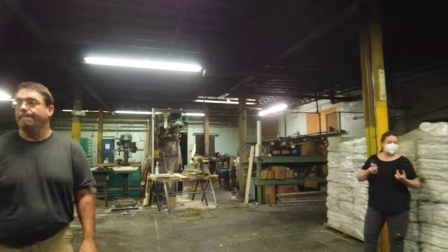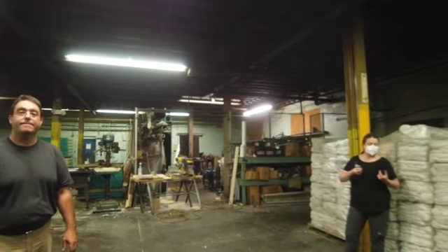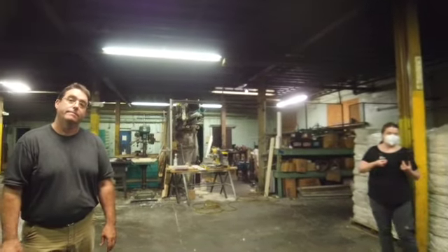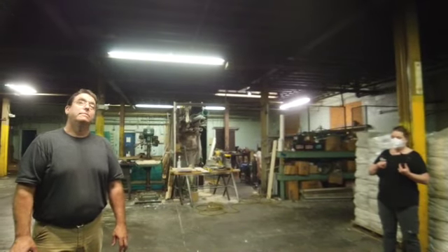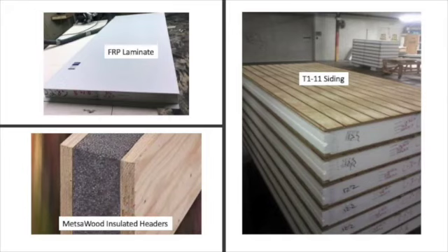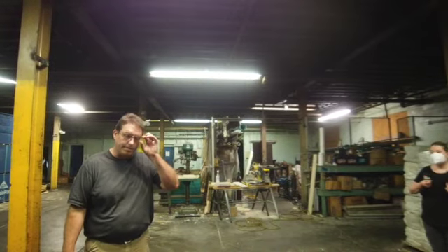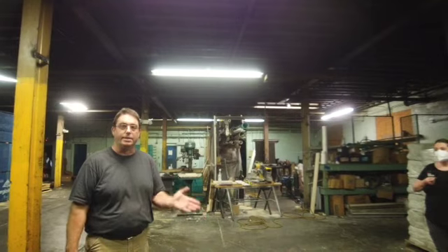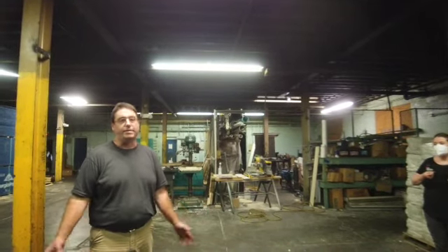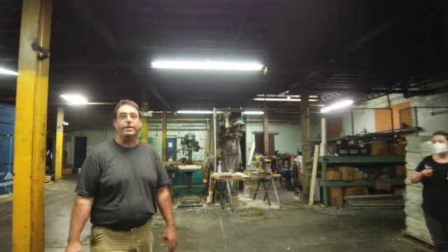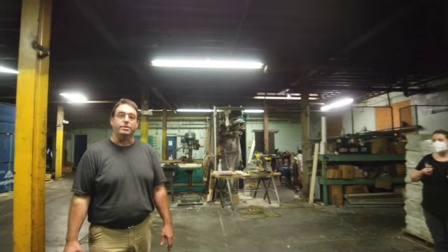And I know it's possible, but I don't know if you guys do it, to put straight drywall on one side for a non-structural panel. Yeah, we can laminate pretty much anything to the foam. Again, non-structural, but for years people were using what most companies call curtain wall panels, so they have drywall on the interior and OSB on the exterior, and usually for some kind of frame enclosure, timber frame or steel structure enclosure.